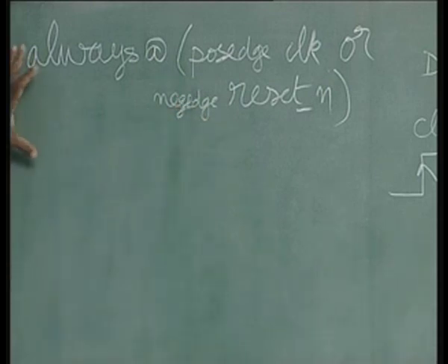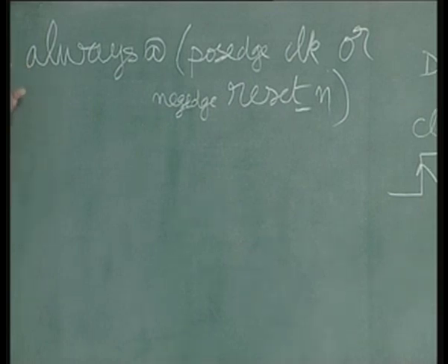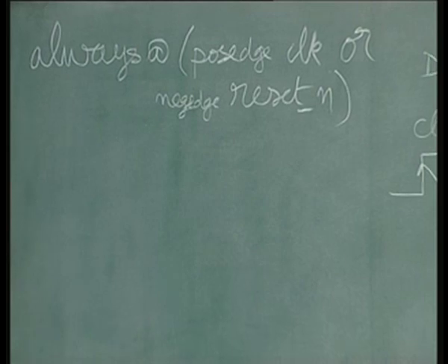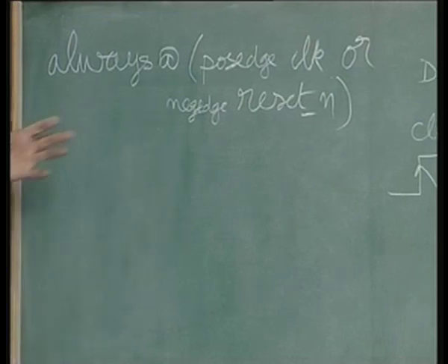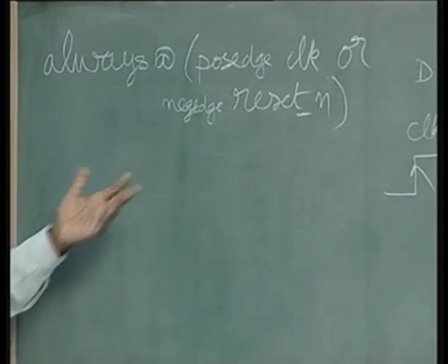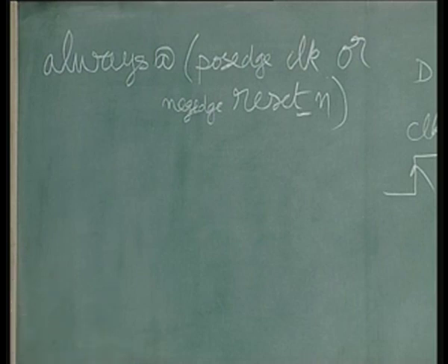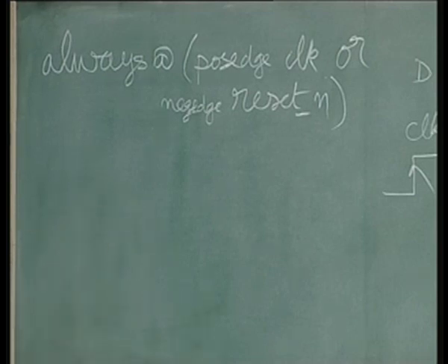Right. So in sequential realization, another name usually encountered for a flip flop is a register. Hereafter we may be referring to a register as such, which simply means either a D flip flop or any other flip flops. Fundamentally, when you see a synthesis tool and finally get the circuit out of it for the code that you have written, you will be seeing only D flip flops in almost all the places.